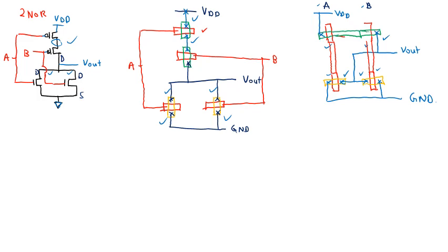You just connect it like this. Okay, so you have it like this, and then in the middle of the NMOS here, you can remove the contact here and here, so you will have to extend this part only. Okay, like this. So in the middle, you just connect only one. So instead of 2 in the previous, we have only 1 and 2 connection. We reduce the capacitance. Okay, this is improved, right?